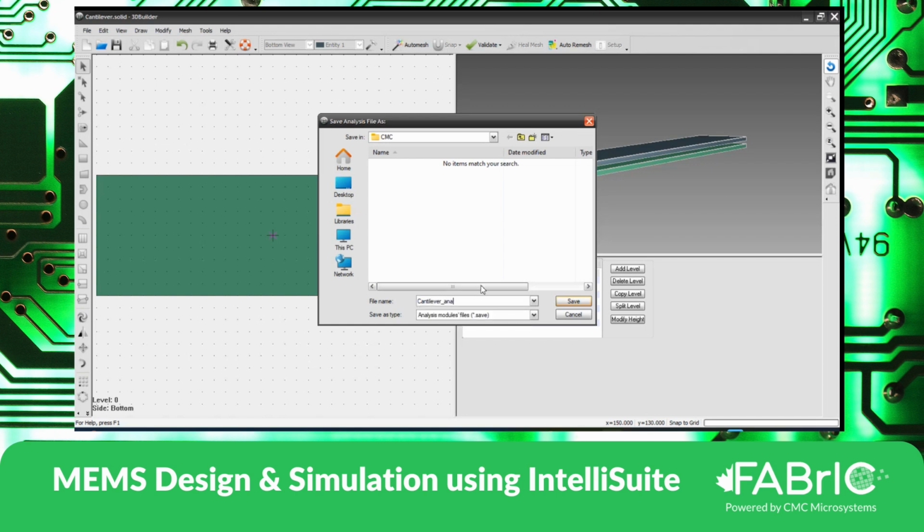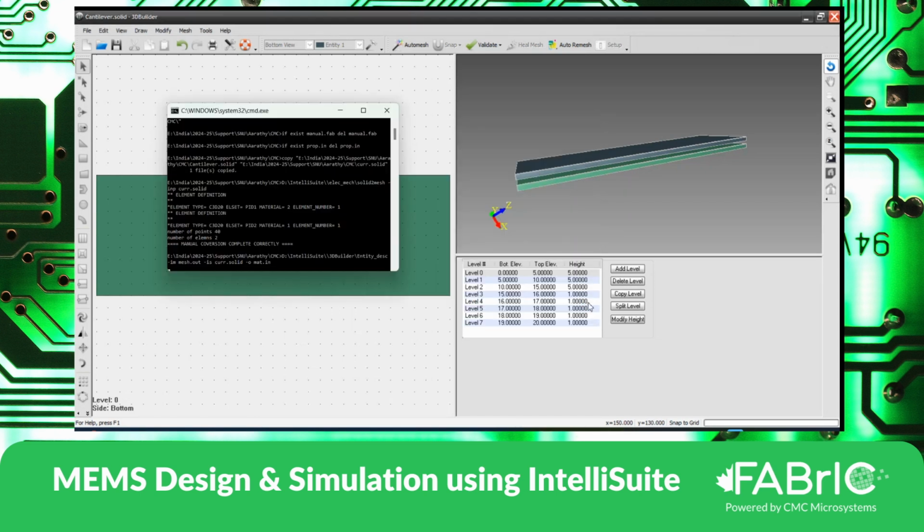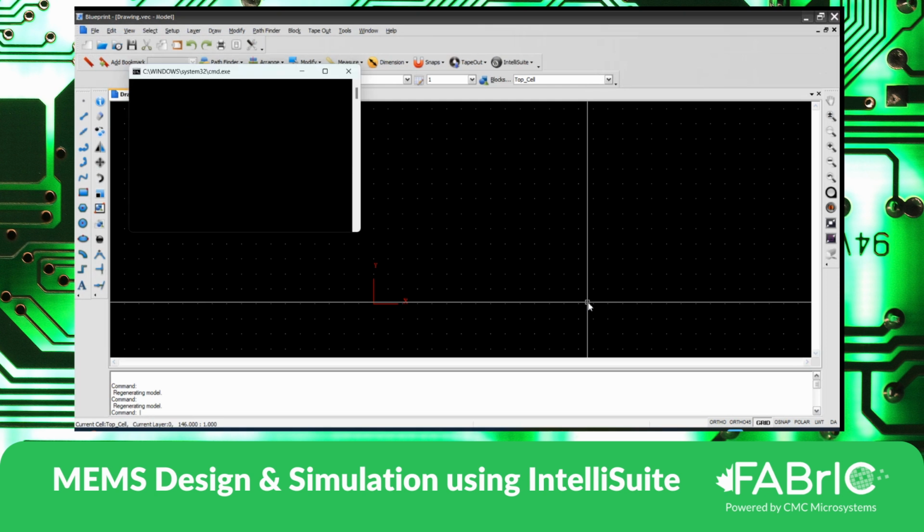There is no condition here to give any file name, but preferably avoid alphanumeric or only numeric file names because the software may pop up some errors during the simulation.